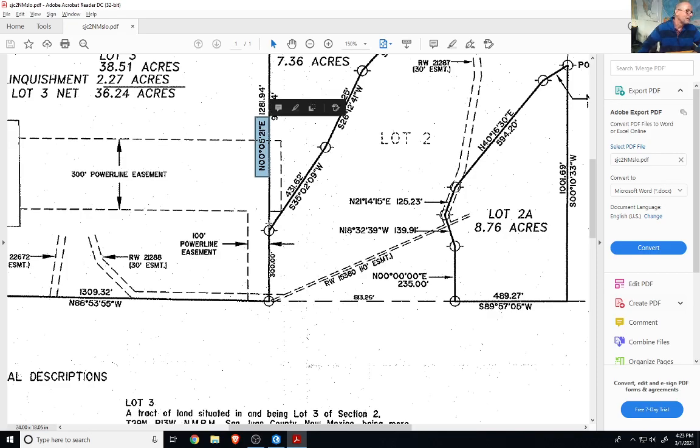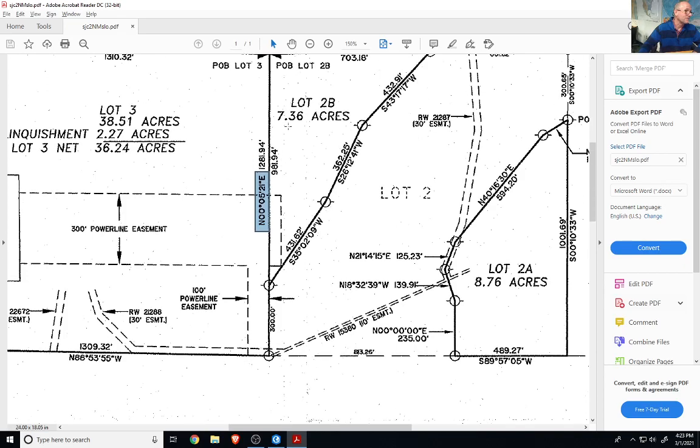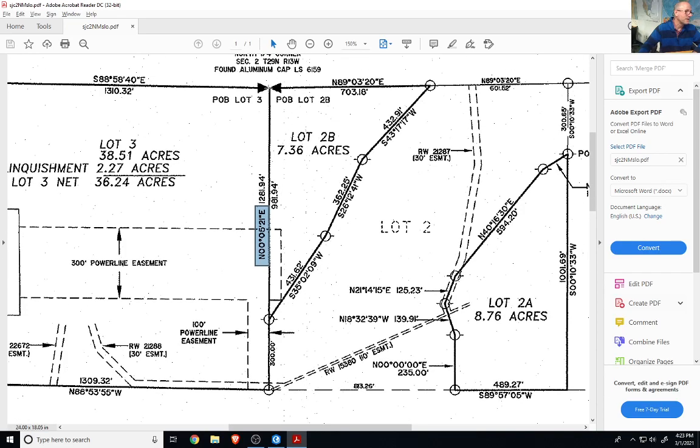And then from there, it would go up to that next vertex, because I've already gotten this point here, so I don't have to type in that same direction for that distance because I've already established that vertex right here. Notice also that this distance 981.94 plus the 300 adds up to the 1281.94. So these two added up at that direction is what you're looking at for that line.